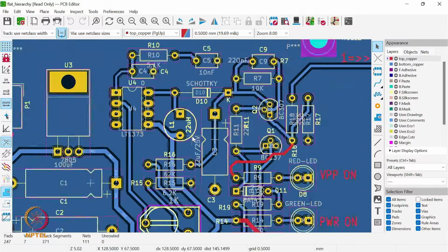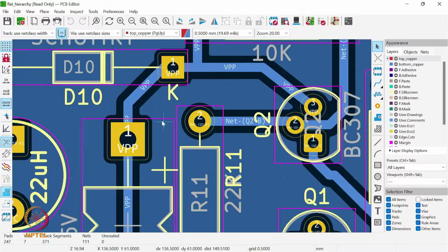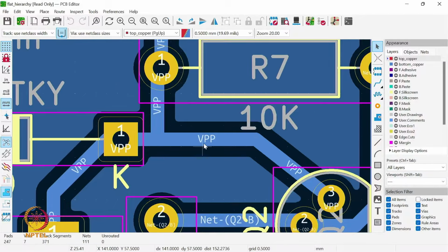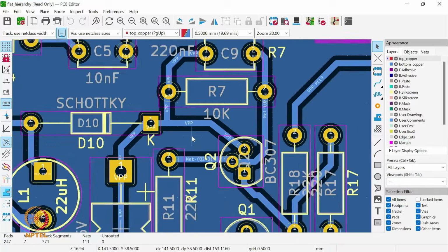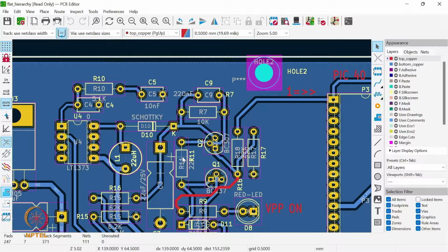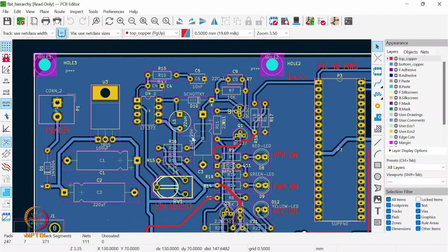For example, this track we have drawn here, and this track just by mistake comes very close to the other track, which is not acceptable sometimes, because during manufacturing, because of certain mishandling or less capability, this track may get shorted to another track. So there are so many design rules which we put in the PCBs to increase the manufacturability.